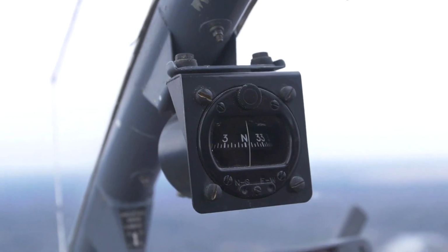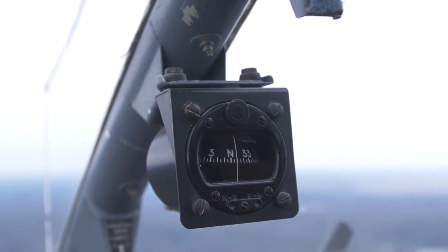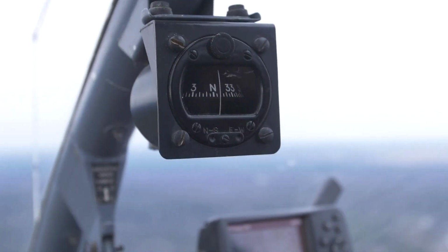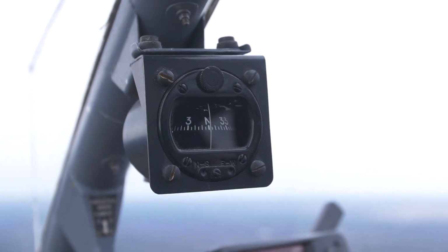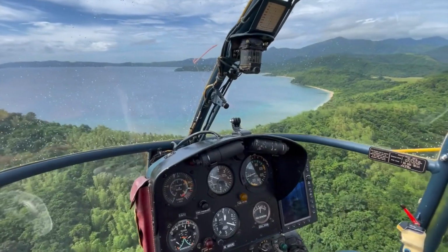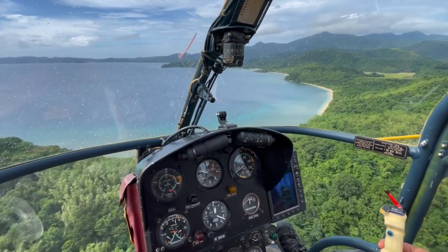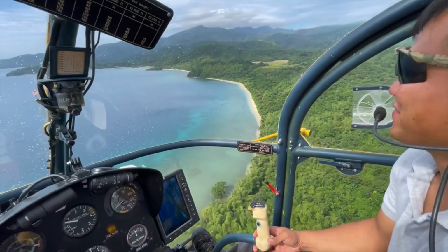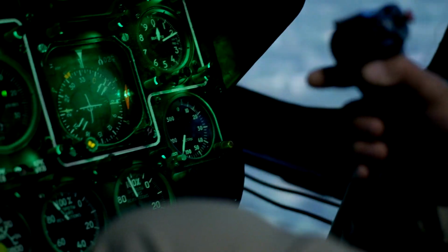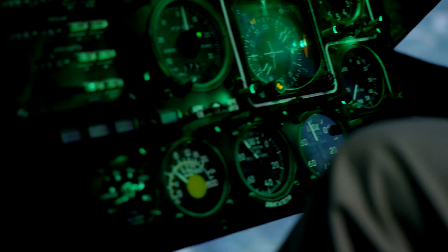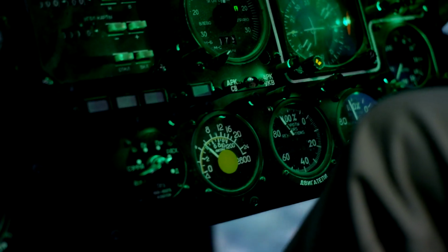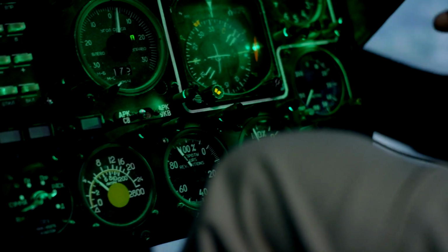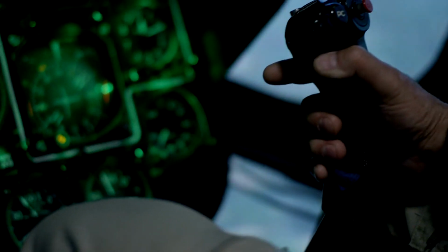The technique involves selecting two references directly in front, aligning with the helicopter, and maintaining this alignment throughout the maneuver. As the maneuver commences, the pilot applies gentle forward pressure on the cyclic, allowing the helicopter to gracefully move forward. To achieve a constant, controlled ground speed, no faster than a brisk walk, the cyclic is carefully returned towards the neutral position. The dance continues, with the pilot maintaining a harmonious balance, constant ground speed with the cyclic, heading with the anti-torque pedals, altitude with the collective, and a steady rhythm with the throttle.